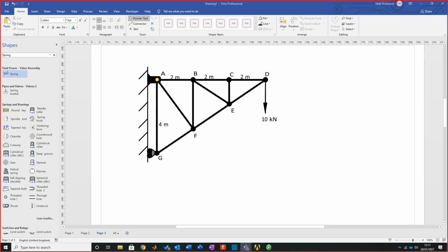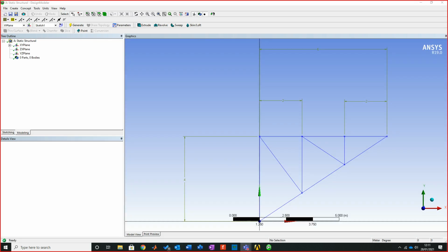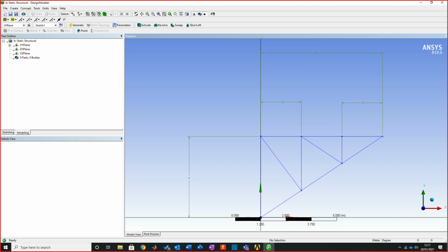We're going to use ANSYS defaults, and we're going to set this drawing up as our sweep point, if you will. So first thing we need to do is tell ANSYS that this isn't just a drawing anymore. We want to call this geometry.